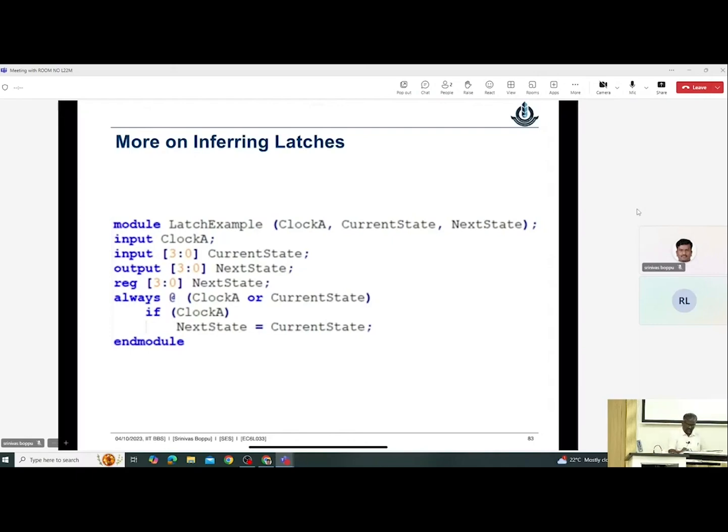Now if you see, as I said, in the hardware I have only wire, a latch and a flip flop. Now what you are saying is that you will not put this one. But again, in your simulation you will get something, but the hardware, somehow it gets the same thing. The tool just generates a warning and most probably will get the same circuit, but the problem is that you will have one behavior in simulation and one behavior in synthesis. Okay, good.